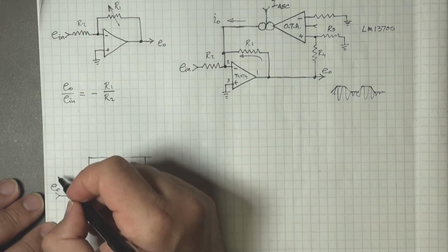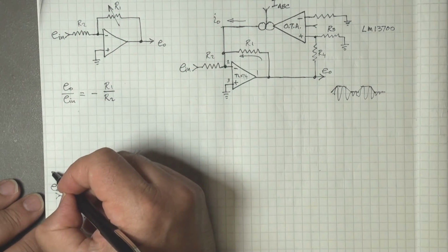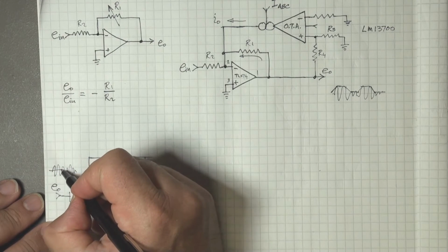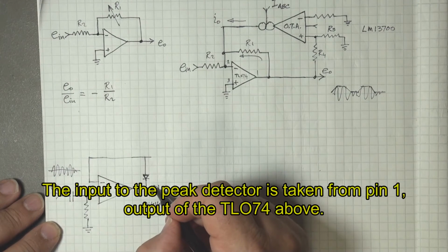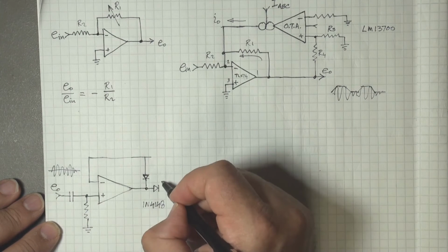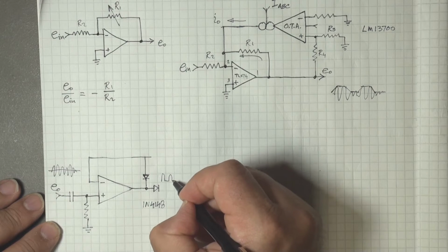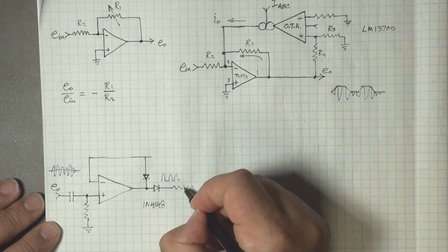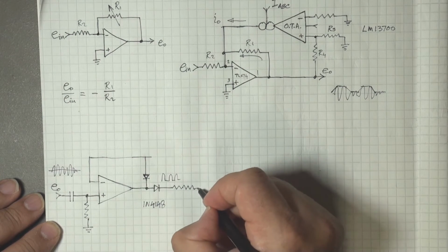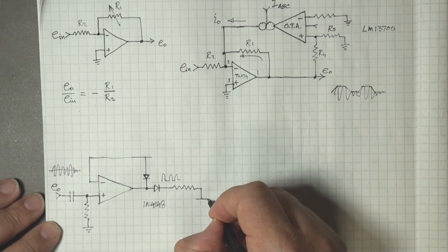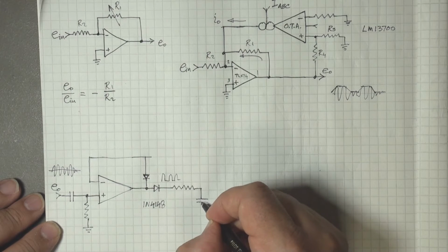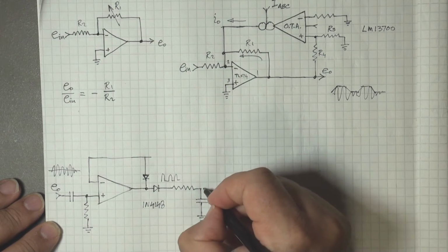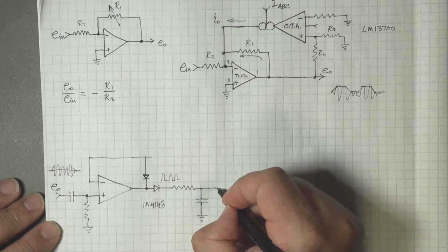Okay, as the voltage swings of the microphone preamplifier output change about a DC value, this diode here is going to pass only the positive current peaks, and we'll pass it through a resistor and another low-pass filter, a capacitor to ground with a parallel resistor.